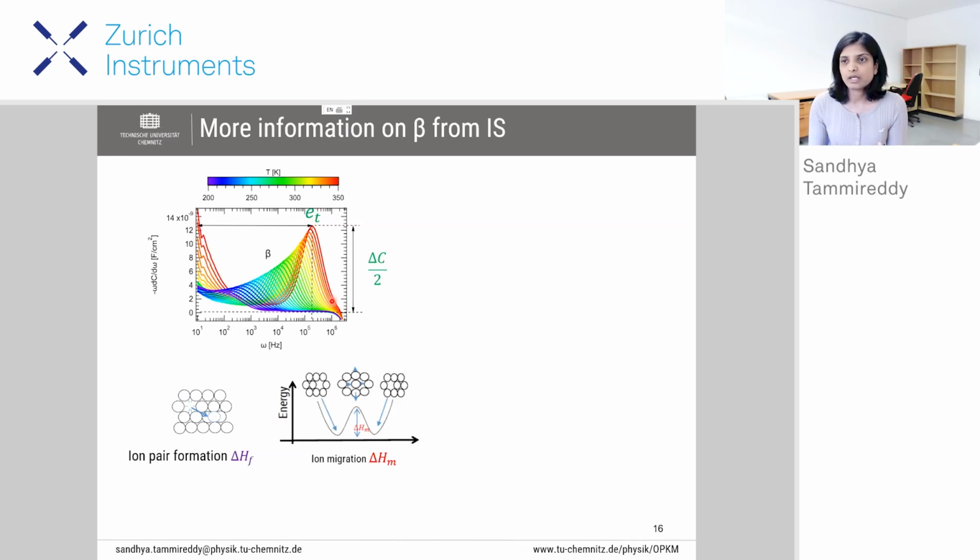When you supply your crystal with a proper amount of energy through temperature or while you're fabricating your device, there might be a point where the neighboring bonds will break and the atom will become free of the neighboring bonds. And it will move to a certain location, leaving a vacant site or an interstitial site behind. So by the process of creating one defect, you will always form a defect pair, whether it's a vacancy pair or a vacancy-interstitial pair.